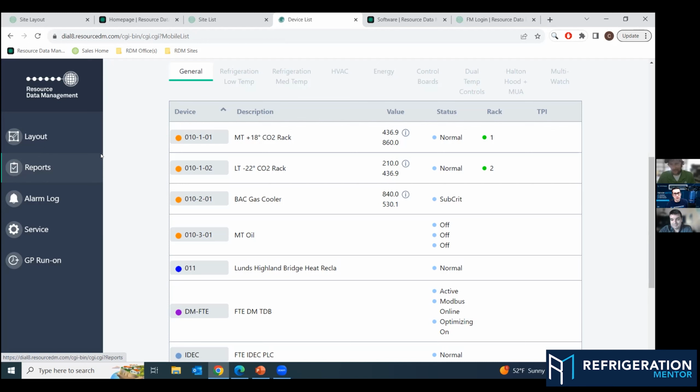And this is another thing I've learned. You have a controller that'll do 3 valves, one controller for 3 valves on a case, for example. But those different coils may be set up differently. Have you noticed this, Cody? Because I've had guys say, I took the program and jammed it into all the cases because we know it's on the same rack and the same suction. But even in that one case, you could have different pressures. Maybe it's a design by the OEM. Maybe the airflow across the coil on the end is different than the one in the middle. So if you just put the exact same parameters in, you might not be getting the most efficient running case.